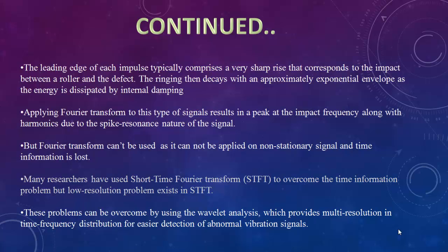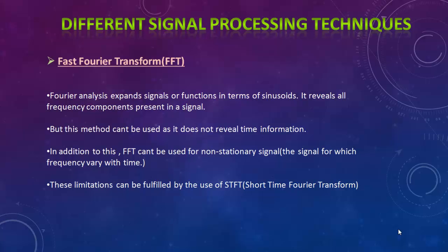Many researchers have used short-time Fourier transform to overcome this time information problem, but a low-resolution problem exists in STFT. These problems can be overcome by using wavelet analysis, which provides multi-resolution in time-frequency distribution for easier detection of abnormal vibration signals. Now we will look at the different signal processing techniques.